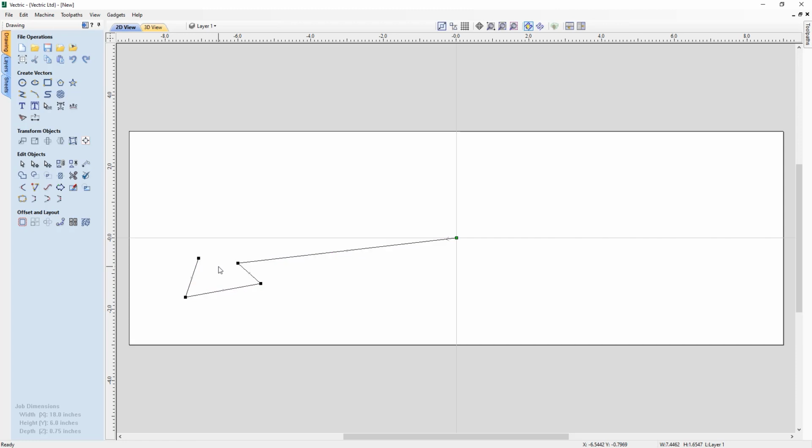So that's N on my keyboard. Now I've got lots of different things I can do here. I can hover over top of the line segment and press my right mouse button. I'm going to get this great little pop-up here that's going to give me the quick keys for some options. I can convert this line segment into a Bezier, into an arc.